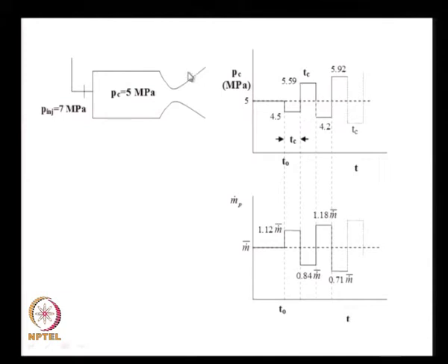This higher pressure led to starvation of propellant, and therefore after some time the propellant flow rate decreased. When this came up you had a net decrease in pressure, and what did we find? That the pressure amplitudes kept on increasing with time.